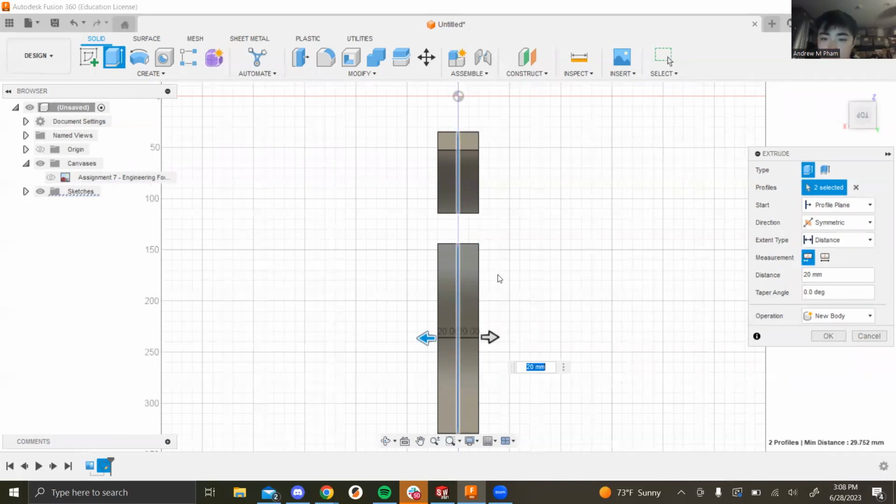And what it will do is it will mirror it and extrude it from both ways, right? And now you see it's symmetric over the axis or over the plane that we modeled it on. So when we copy it around the circle later, it'll be nice and even.